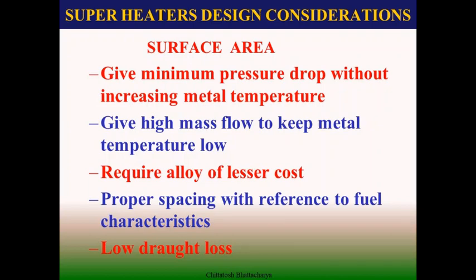In general, an average 30 to 35 degree temperature difference is there between the tube metal and the superheated steam along the flow passage.